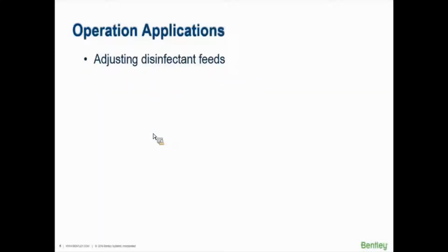It could help you, again, decide your disinfectant levels, how much chlorine you should be dosing to get the optimal residual out in the system, out in tanks. But as we get into the water quality modeling in a bit more detail, it doesn't mean it's just going to be very easy, it's going to spit out the number. You as the hydraulic modeler are going to have to do some legwork and calibrate the model to make sure that what the model's predicting is actually realistic. So we're going to get into a lot more detail on that here in this talk, but this is just the fundamental, again, scratching the surface of water quality modeling.